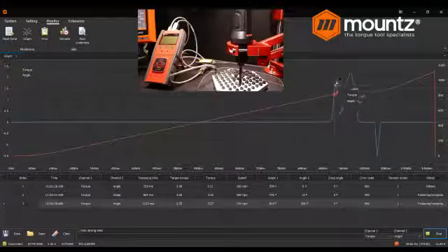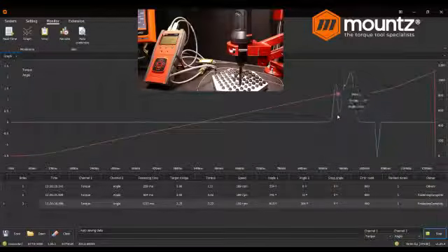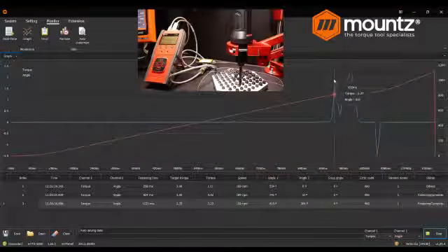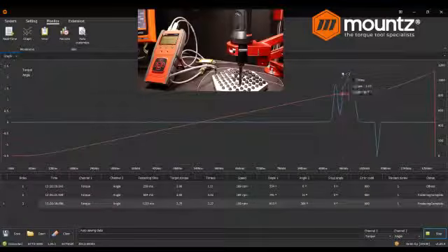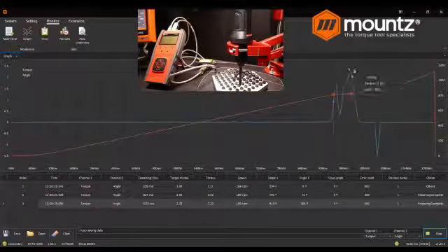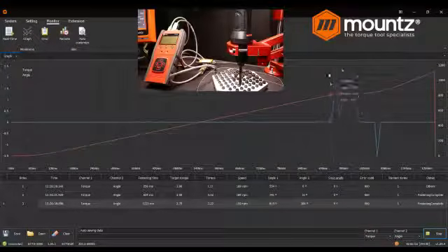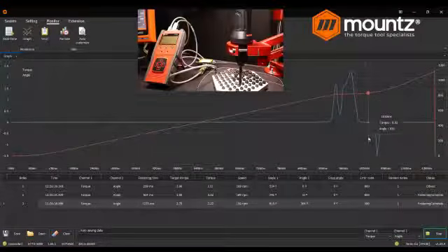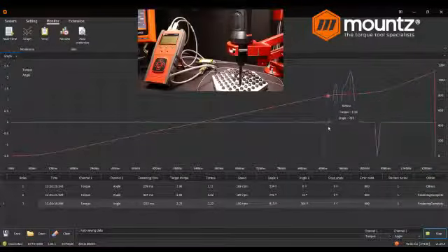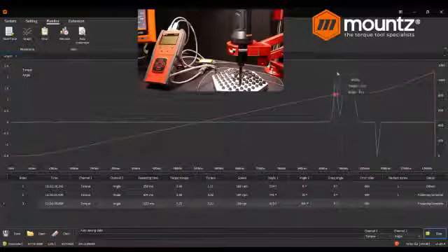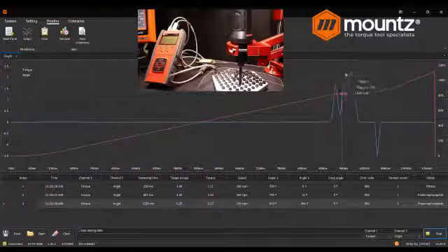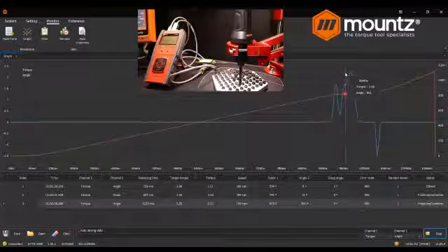So if we were to look at these 2 points here, and instead of the image dropping down, we saw this kind of flatten out. So if this first peak and this second peak here were kind of matching, and we didn't see the valley, it would be almost like the letter N. That's typically what you would see once the curve starts to flatten out. That's where we see the yield point. And that's where you would see the failure.